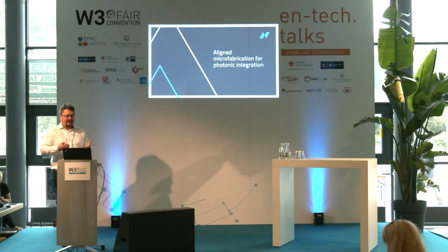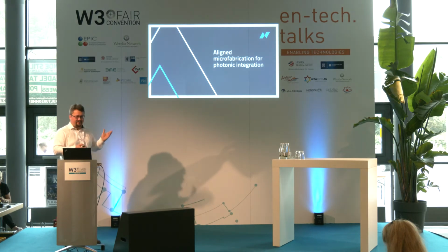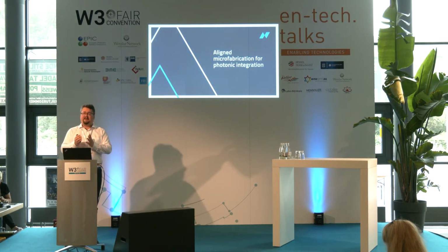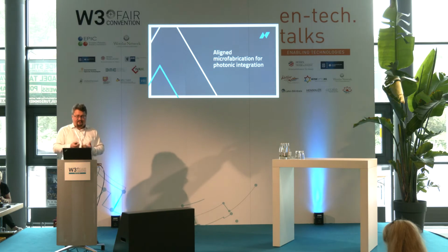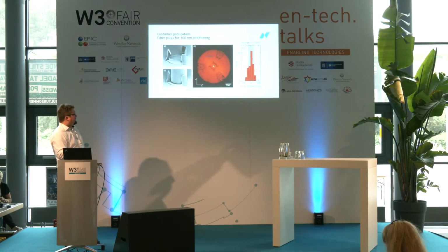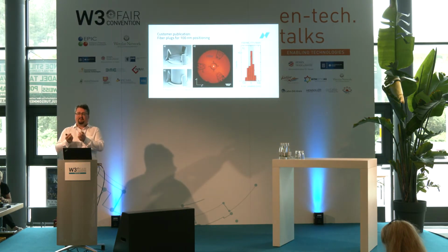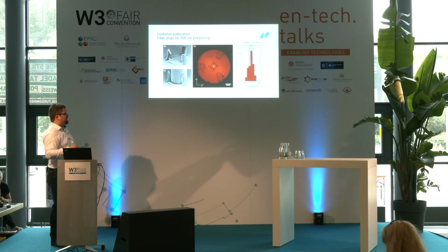But let's come to the application. And like I said, I'm going to talk about aligned microfabrication with the application photonic integration. So if you can print tiny polymer objects with high precision, you could just use them as mechanical coupling agents. And this is actually happening.